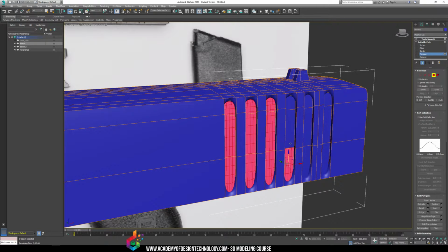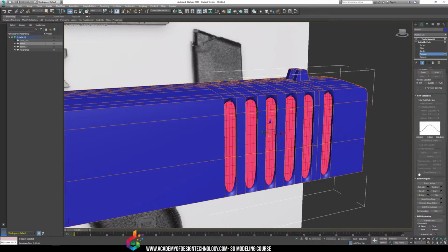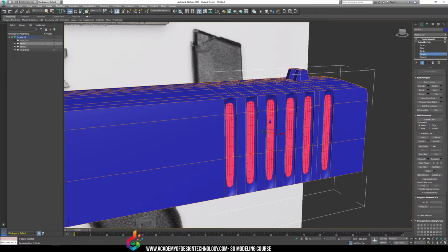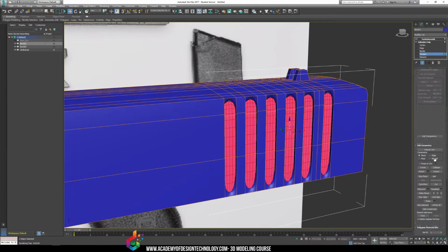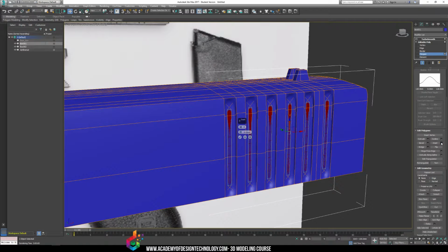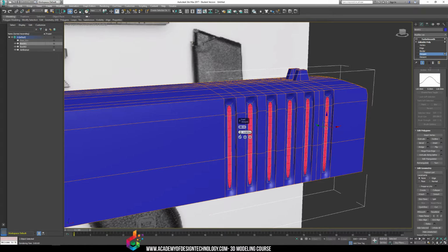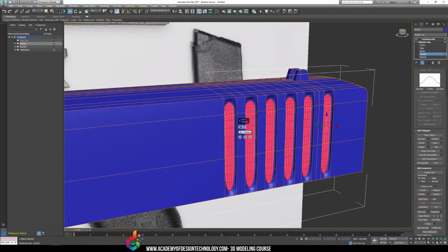So if I go click on these, like this, and I change the smoothing group number here, I change it from 1, I'm going to make it 20. You can see we still run into that issue, right? And that's because of lack of detail. But if I add an inset, then change the inset amount, of course, it becomes a little less rounded.